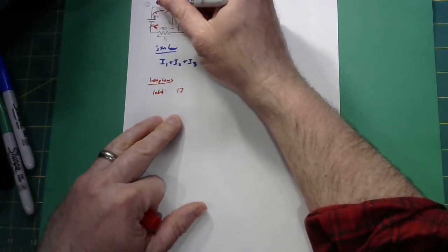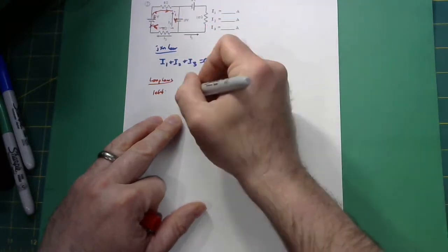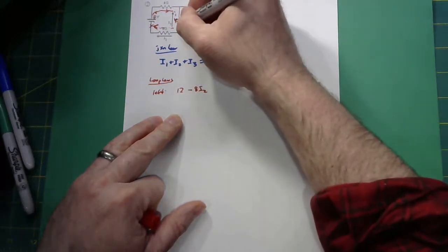So I'm going from before it loses the energy to after it goes through the resistor and loses the energy of those charges. So we're going to go down potential. So we're going to go down 8 I2. And then we're going to go backwards through that battery.